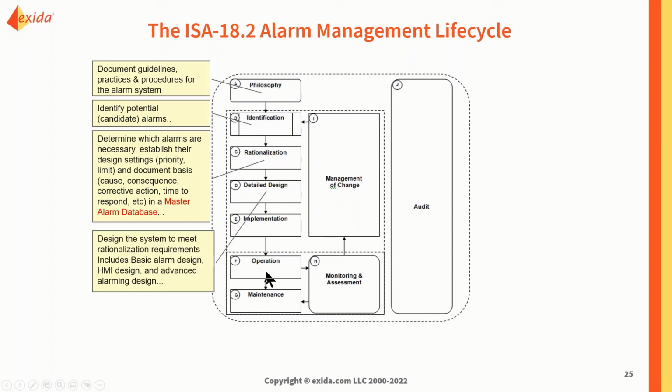And after the rationalization process, we're going to go into a more detailed design process, which is related to some kind of programming of the alarms. For example, you have a compressor trip. Usually, when a compressor trips, that's going to create a lot of associated alarms, like the vibration alarms, high pressure, low pressure. They can come in both, depending on how you set them up, whether they're on discharge or whether they're on the inflow into the compressor.